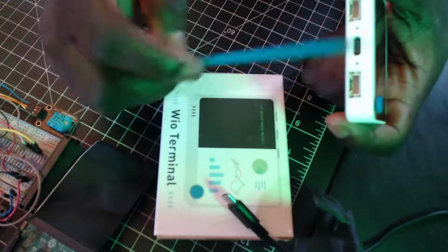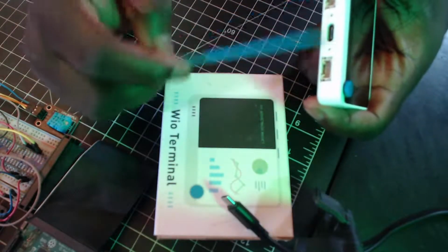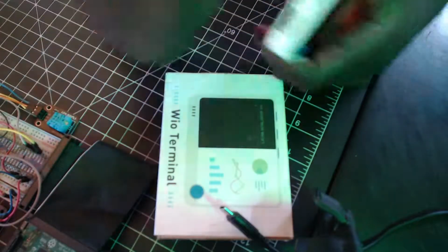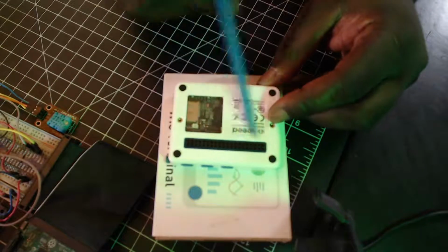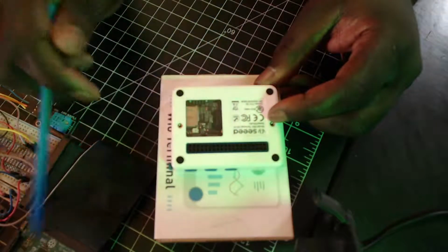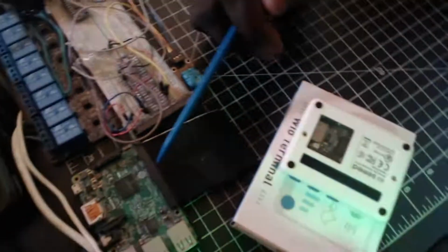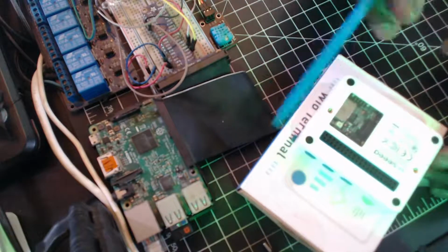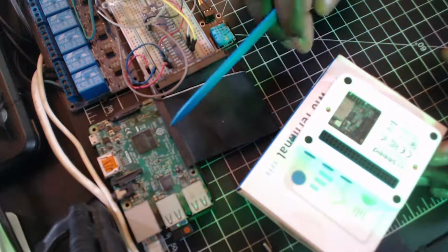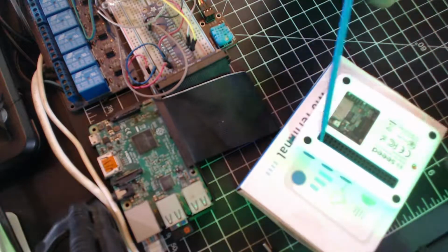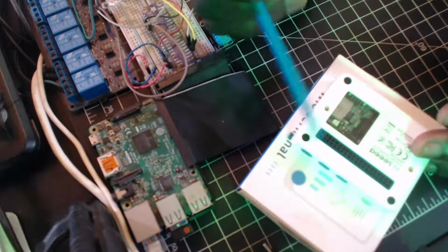So you can see we have two Grove ports here. One is I2C, one is digital, but both can be used as digital. And if you look behind it, it shares almost the same 40 pin IO pin layout just like you have in the Raspberry Pi. If I swing here, you realize that I have a Raspberry Pi here, and this also uses the 40 pin. It's the same thing here. So pretty much if you want to add extra sensors, the same thing, you can reference this.